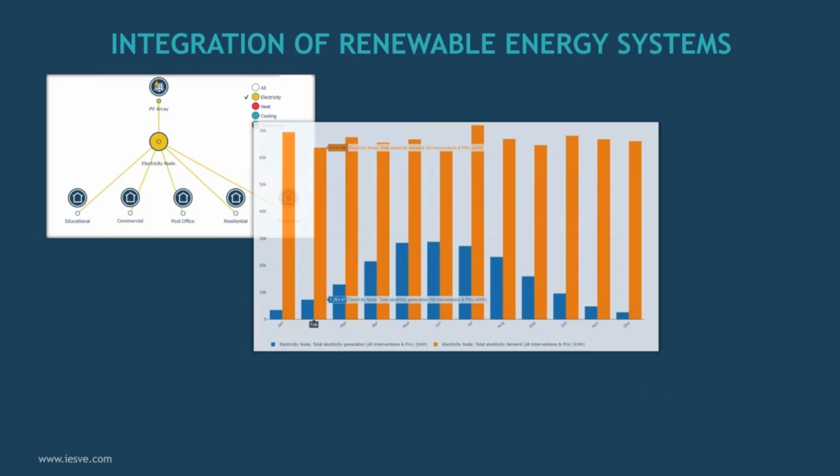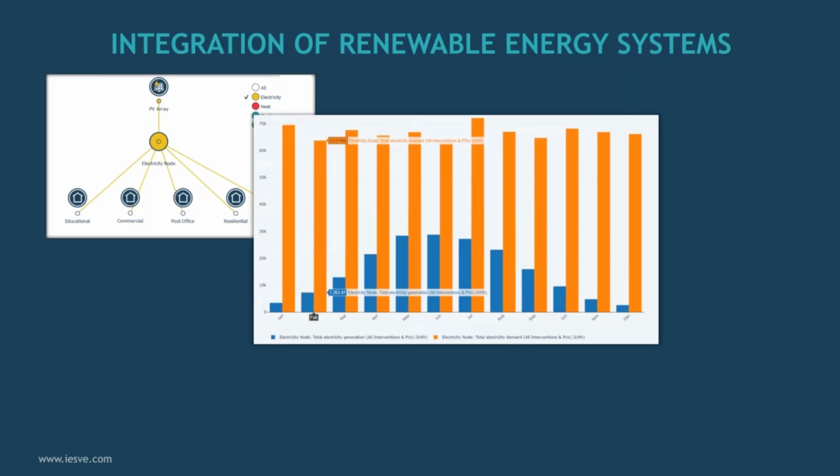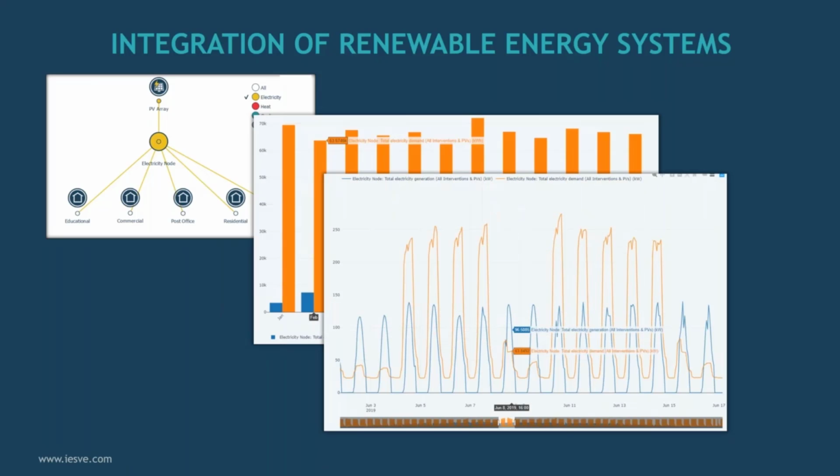After doing some quick simulation, we were able to understand that there is quite a good production that can be retrieved during the summer months. Obviously, on a monthly picture like this, it's not always ideal to run a simulation and just say, okay, my demand is higher than my generation, so I'm not wasting any energy. That's usually what's done in a very simple and quick PV and solar analysis. But actually, thanks to the tool, we were able to do this at an hourly level.